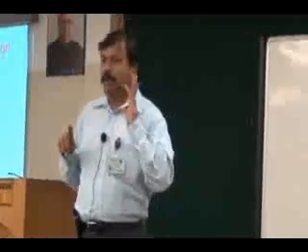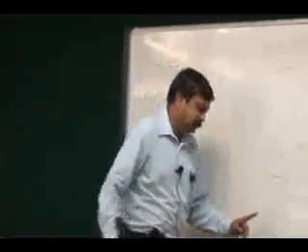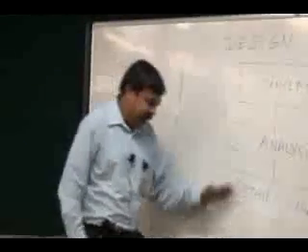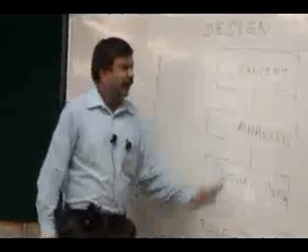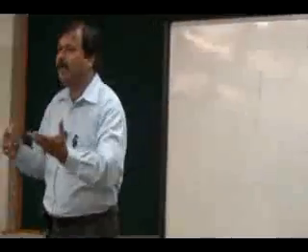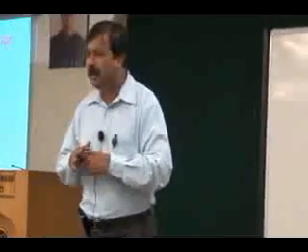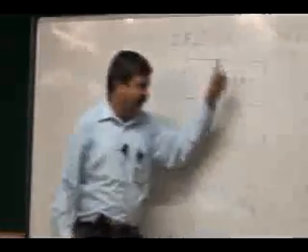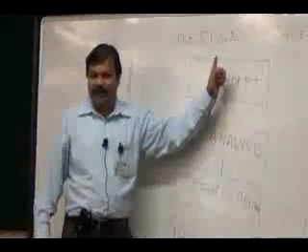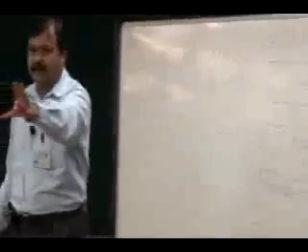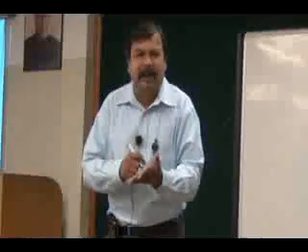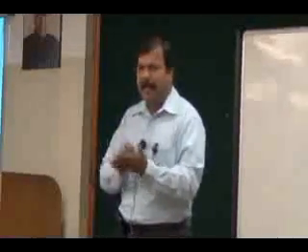But there is one big problem with sequential engineering. Suppose at some stage you encounter a problem. You have arrived at the detailed design, you have made tools, and when you try to manufacture it, it poses a lot of problems. It is very difficult to make. You realize that only then. All these activities were carried out by traditional design engineers. You give the drawing to the manufacturing engineer. He says, sir, this particular part cannot be manufactured, or it can be manufactured, but it will be very expensive to make.